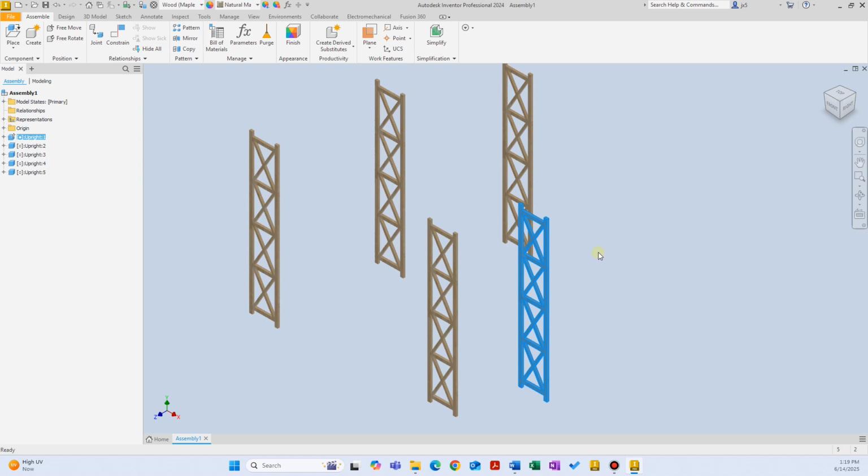Why is that important? Because every time you're creating an assembly, you add the components and then you position them, you mate them together, you attach them together. So you need a reference component to use as a reference point, so you can use that component to attach all the other components. That means at least one component should be grounded.